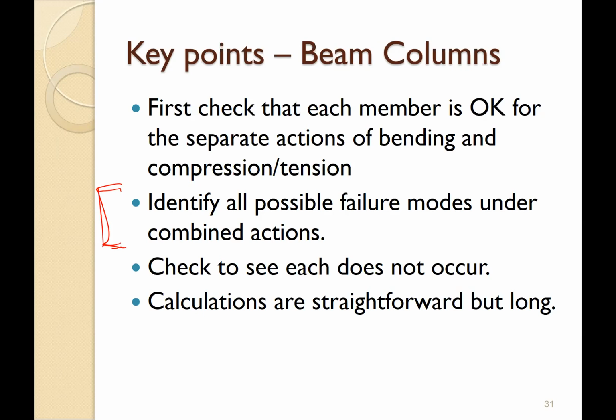In plane will be a little bit better, because if you consider major axis buckling, it is still better. Why? Because I about that axis is much higher than I about YY. So it is much more resistive in buckling. But when you consider out of plane, the buckling will be about the worst, that means the minor axis YY. So your capacity will be reduced again.